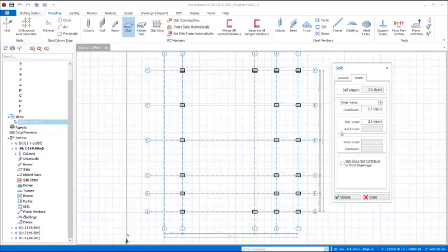If you check very well, the roof load is not enabled. Okay, the snow load is also not enabled. The rain load is also not enabled because we did not enable it in the loading combination properties. That is why. So after which, we now start to insert our slab.